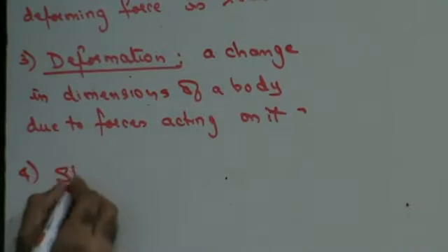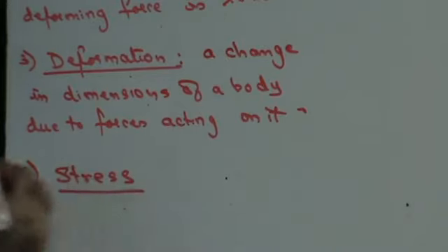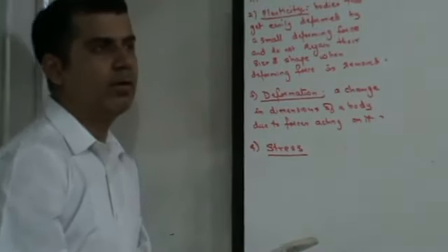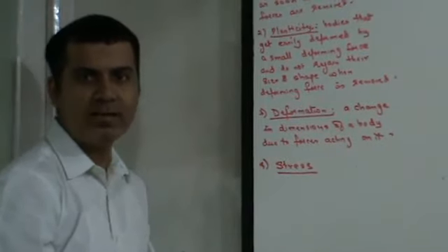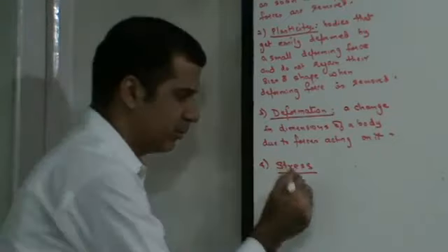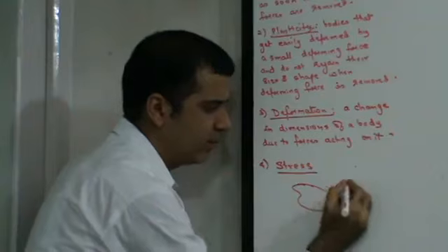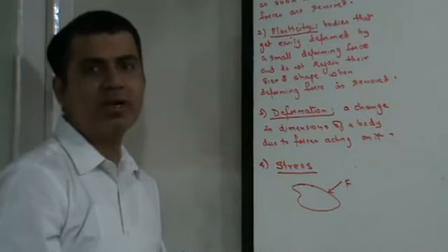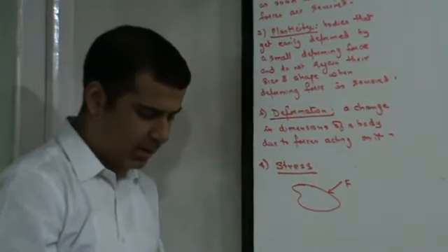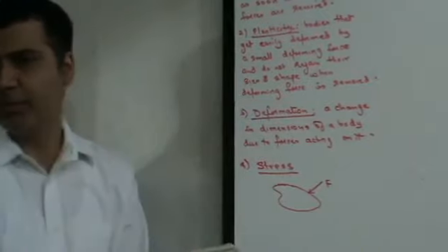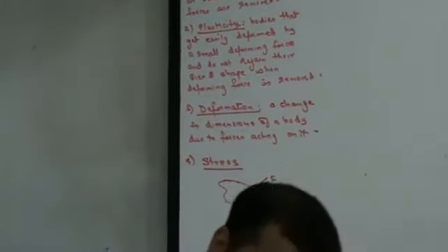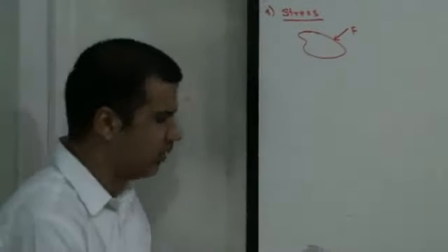what do we understand by stress? Very important word. What is stress? Now, when I apply force to a body, the body gets deformed, right? Suppose if this is the body, and if I am applying some force on this body, the body is going to get deformed, right? How much is the force that is being applied per unit area is called stress. Stress is defined as the deforming force per unit area.